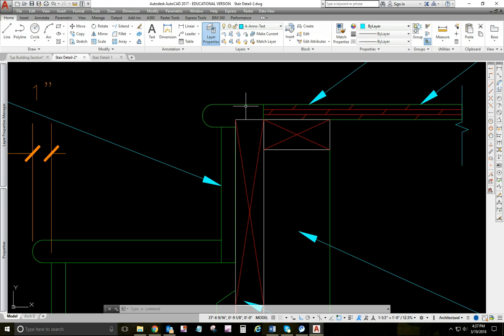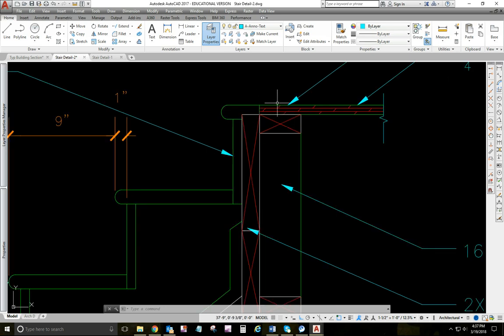And then your carpet would just cover that and stop with a transition. Or if you have some kind of finished floor up here, wood, finish, then this nosing would actually be raised up and sit on top of the subfloor so that the top of this nosing is level with the top of your finished floor. Okay, this is why you need to know what kind of finished floor you have when you go to do your stair calculations. If you don't know, then you calculate based on the subfloor.